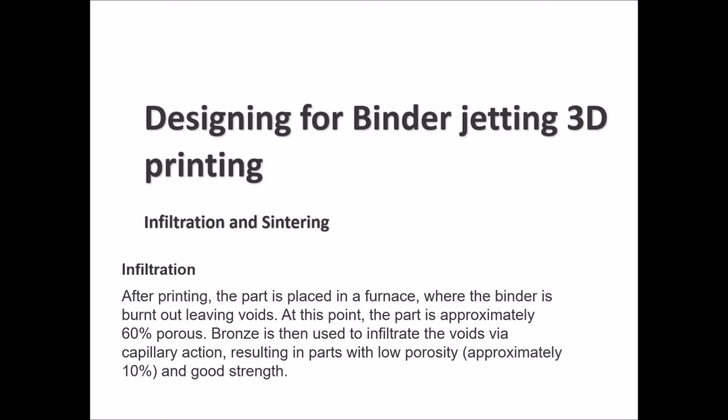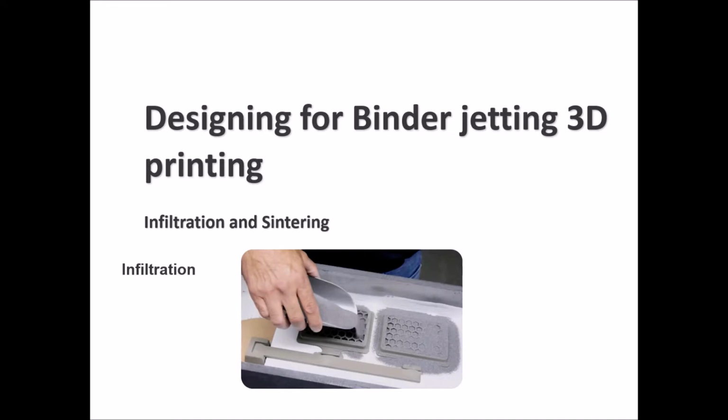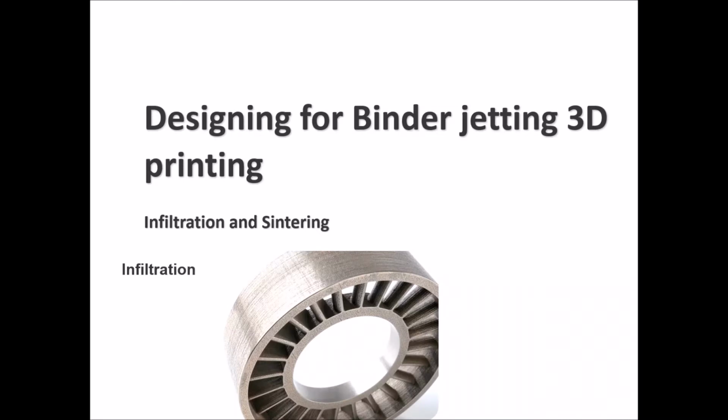At the end, you will have a part that has low porosity of almost 10% and good mechanical strength. You can see here the actual process of infiltration. This is an actual part that's being printed using the binder jetting method and being infiltrated as a post-processing technique.